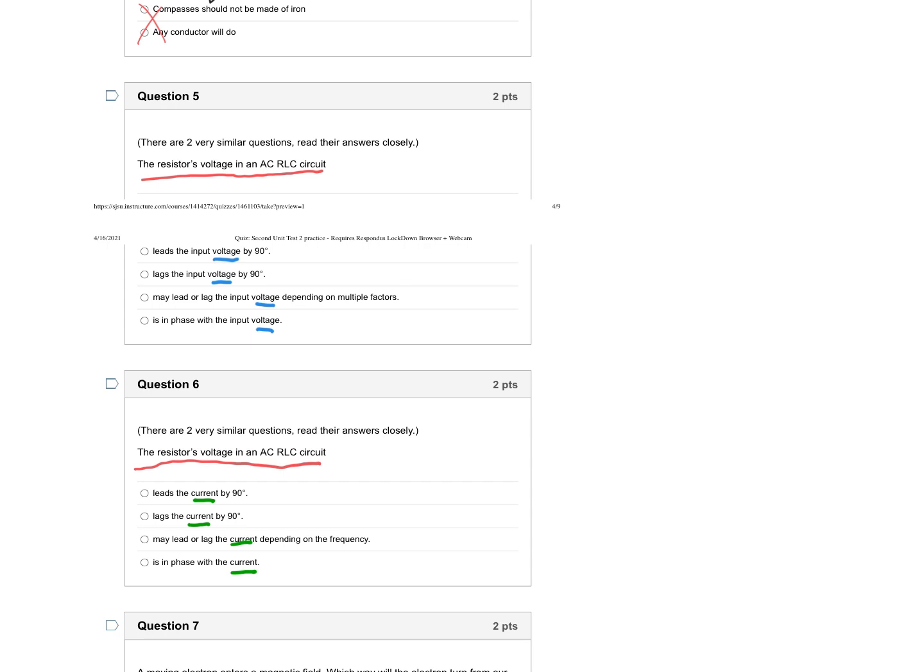I'm going to start by drawing a phasor diagram. Voltage for a resistor, voltage for an inductor, voltage for a capacitor, and then the voltage for the power supply is off like so. Additionally, the direction for the current is the same direction as the resistor. Okay.